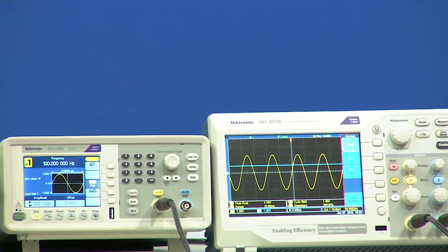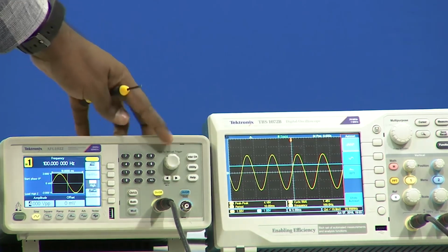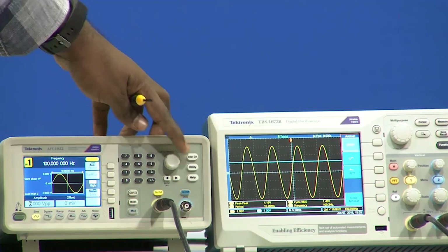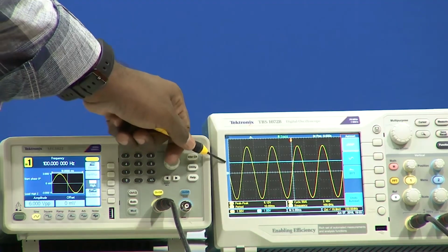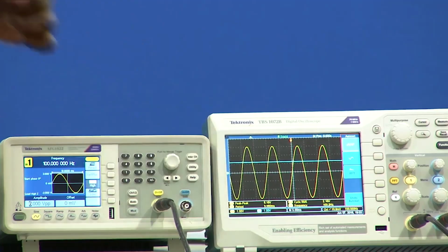So that means when the input keeps on increasing, the threshold value is also increasing. Let me change to some other value, 6, so it is 1.2, right. Either because of the previous loading or because of the tolerances of the resistance values, the expected and actual threshold values are a little different, but by putting a potentiometer, we can even set it to the required threshold value.